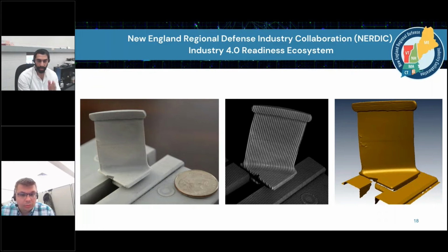So you see originally that the projected pattern is straight lines, but what's coming back into the system are deformed lines. And because the system is calibrated, in other words, in the sensor, it knows the distance between the camera and the projector. It knows the angle between them. It knows the distortion characteristics of the lens for both camera and projector. The only real unknown is the shape of the part, and this is what the scanner solves for, knowing all the other information that's contained in the calibration. And so all the way on the right, you see the 3D reconstructed image of that surface.